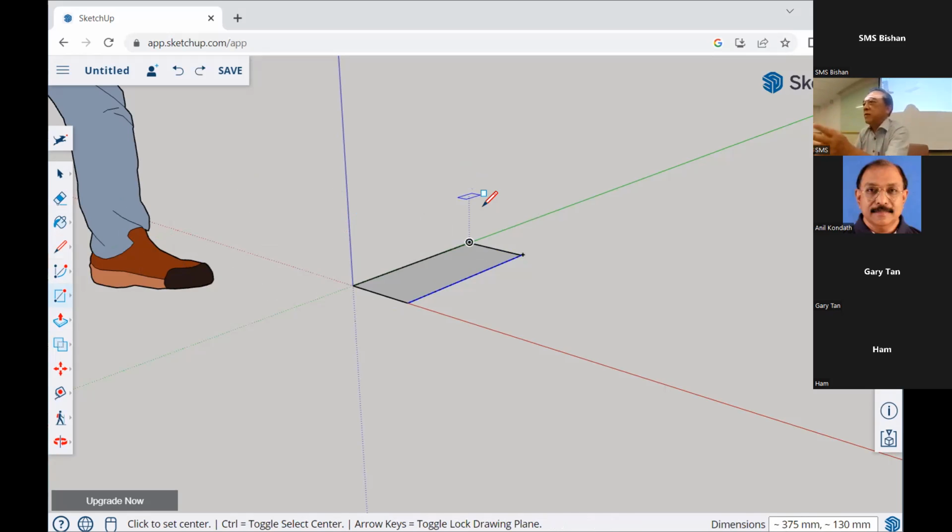So every time you move, let's say you want to draw a square, you move, then you don't want, you hit the escape key. But if you already release the mouse, the object is created, so you must press Ctrl Z to undo. But if you click and the mouse hasn't released, you hit escape. Then it's okay. Then you release. Then okay, fine.